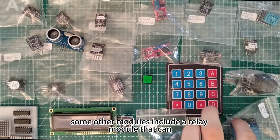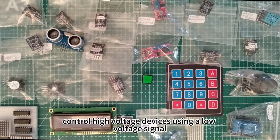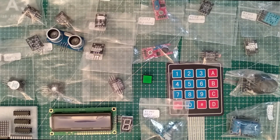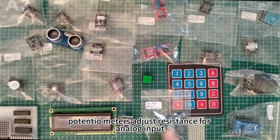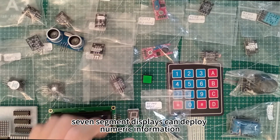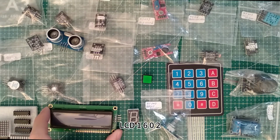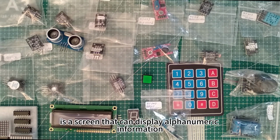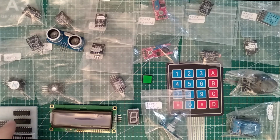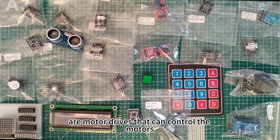Some other modules include a relay module that can control high voltage devices using a low voltage signal. Potentiometers adjust resistance for analog input. 7-segment displays can display numeric information. LCD 1602 is a screen that can display alphanumeric information. Stepper and DC motor drives are motor drives that can control the motors.